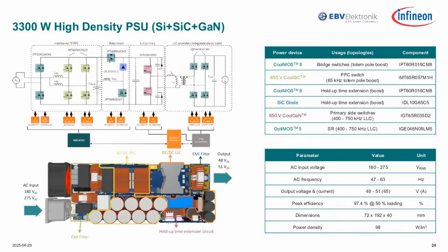So silicon carbide is a good selection in the PFC totem pole. In the slow leg, the focus is just on RDS(on), with no switching performance requirement.